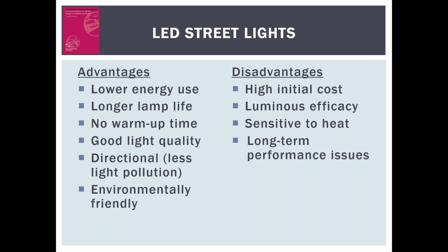Information from a 2012 Illinois DOT roadway report says that at present, streetlight applications mostly involve high-intensity discharge sources such as metal halide lamps and high-pressure sodium lamps. Although high-intensity discharge sources such as high-pressure sodium and metal halide are energy-efficient sources with high lumen efficacy, they also have some performance drawbacks, such as low color rendering abilities, low lumen maintenance compared to LEDs, and longer time required to restrike after a power interruption.